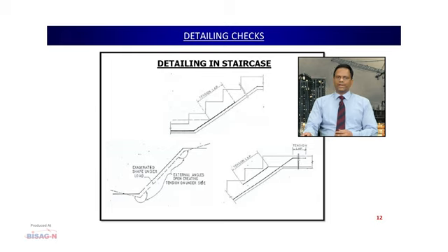We have to provide the tension lap. Now, you can see this bar is provided or taken beyond this, which is called the tension lap. That may not be the requirement of the main steel, but to give the tension lap, this bar needs to be extended up to this. Here we can see this is the tension lap that is given; this bar is taken here and given a bend, that is the tension lap. Similarly, this bar is taken and bent over here, this is the tension lap. That means, under the load, when this joint is opening up, this tension lap is going to arrest that load and resist the cracking.